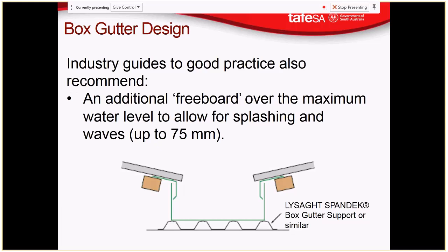Typically when we draw construction details for that scenario, we've got our box cutter here like that, and it's been drawn with a little gap in there. When we draw something like that, we draw it so it can actually be seen. What we are specifying in real life is that the piece of metal pushes against that bit, so we would want it installed so that the tension of that metal is pushing against this side. Now that's not going to provide us a seal by any reliable standard, but